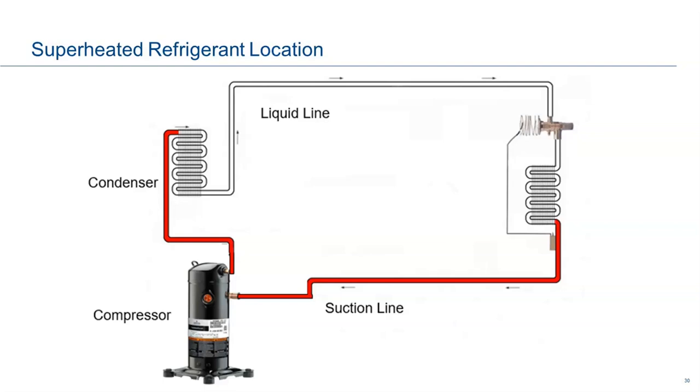Now, if it's above 225, let's say it's 235, does that mean the compressor's bad? Of course not. It just means we need to go back here and take our temperature reading. Maybe this is too hot, and then we're going to start backtracking. We may find right down here that this metering device isn't working right, and it's starving the evaporator, and our superheat's starting too early.